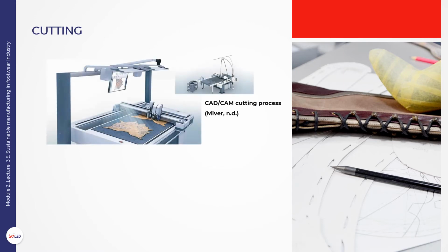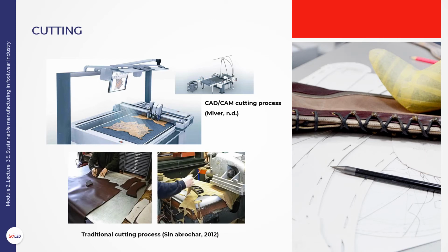Cutting. Currently, die cutting tables are the most widely used. CAM machines are used for taking samples due to their great flexibility. The CAD system communicates the geometric data of the pieces to be cut to the CAM cutting table. The material, leather, is placed in the work area of the cutting table and the pieces are projected on the material. The most important feature is that the positioning, nesting, of the pieces to be cut can be changed several times until the optimal final cut design is found.